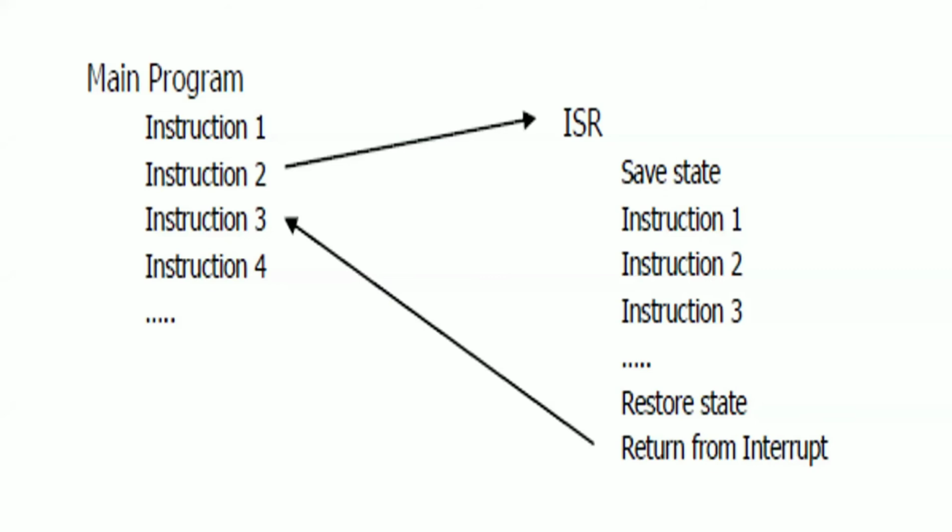If you call a function, you go to the function, execute the code, and again come back to the main code. Similarly here, whenever you get an interrupt, the interrupt service routine has some code, that is a set of instructions, that will be executed. Once that program is executed, it comes back to your main program. This is nothing but the interrupts. And we have two external interrupts, that means externally we can interrupt your microcontroller in two different ways.